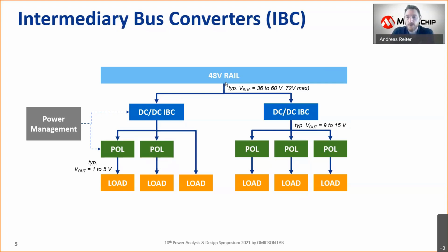So we have multiple conversion points, and obviously when a load has a high demand and starts to create a load profile, the point of load is the first point that needs to correct the voltage. But there's always a reflection of that load profile, which also gets onto the bus.